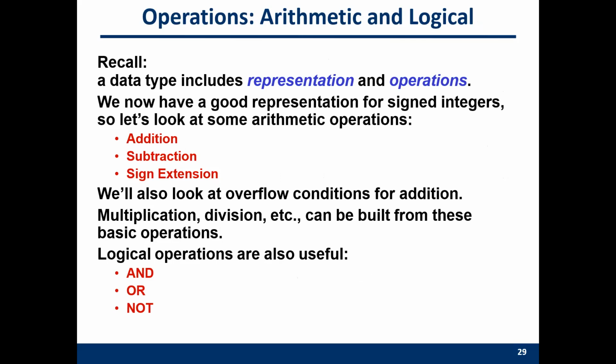So now you can convert a binary number to its decimal representation and a decimal number to its binary representation. And you can represent unsigned integers and signed integers, particularly if the number is negative, using two's complement representation. The next step is to do more operations, arithmetic operations and logic operations, on these numbers.